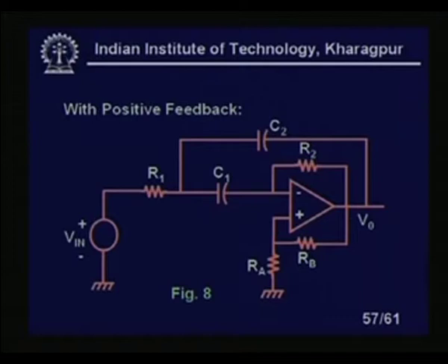You see that to make the circuit stable I do not need this positive feedback, this we have discussed when we were discussing the general enhanced negative feedback topology. This is called the negative feedback with positive feedback, or there is another name, we call it enhanced negative feedback topology. Here we are giving a certain amount of positive feedback, and you will get some great advantage if you give a certain amount of positive feedback in a negative feedback topology, that will be discussed now.